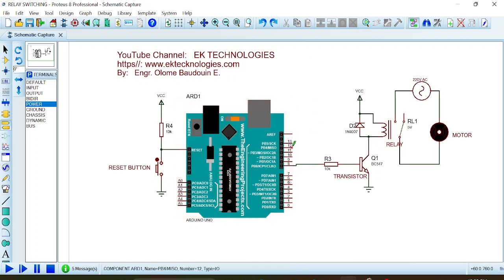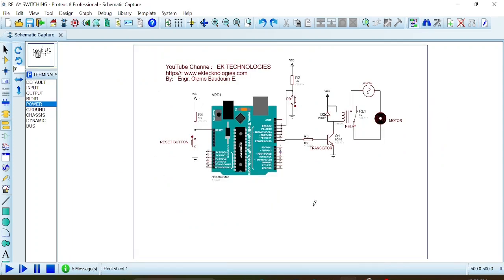So I would like to connect the control push button to activate the microcontroller on pin 13 as such. Okay. So you make sure you supply it using 5 volt as well. Then I would like to use a LED that will indicate whether the motor is on or off. We'll connect it to any pin. Let's select pin 1.